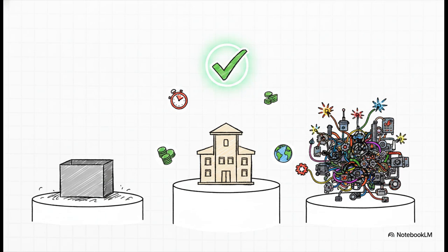So what did they do? They chose what I like to call the Goldilocks solution, the quasi-steady-state model. Based on rigorous European CEN and ISO standards, this monthly calculation method perfectly combines empirical simplicity with high accuracy. It's way better than the steady-state models, but more importantly, it completely eliminates the need for expensive, highly skilled analysts that dynamic simulations demand. This makes the assessments quick, cost-effective, and highly reproducible, which, if you think about it, is exactly what you need if you're trying to scale a green building standard globally.